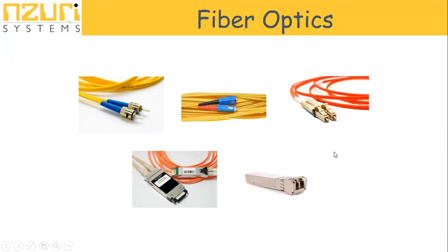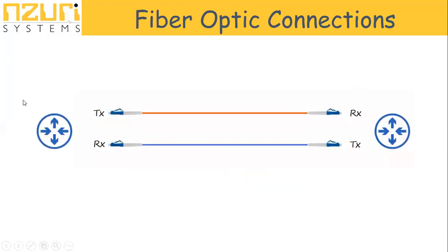That's why you see them coming in different pairs most of the time. So that's a clear scenario of fiber. Always know this: in most of your fiber optics scenarios, you would have your TX. On one side of a router, I'll have a TX going to the RX, and then the other guy will have a TX coming to my RX. That is why you'd always have two different cables being connected in the fiber optic scenario.